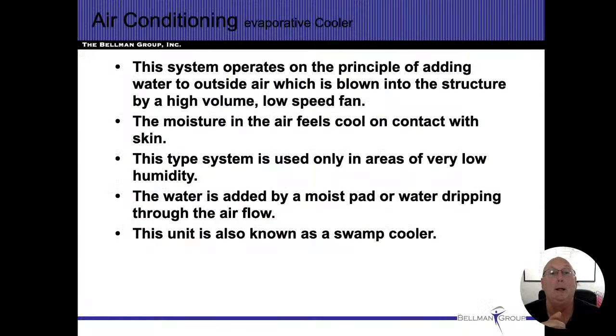All right. The system operates on the principle of water and outside air. We just said that. The moisture feels cool on contact with the skin because it's evaporating. It's only used in very low humidity. Water is added by a moist pad, water dripping. Same type of humidifiers that we use in our own houses, and then more of a nickname than anything else, they call them swamp coolers. You'll hear that as well.